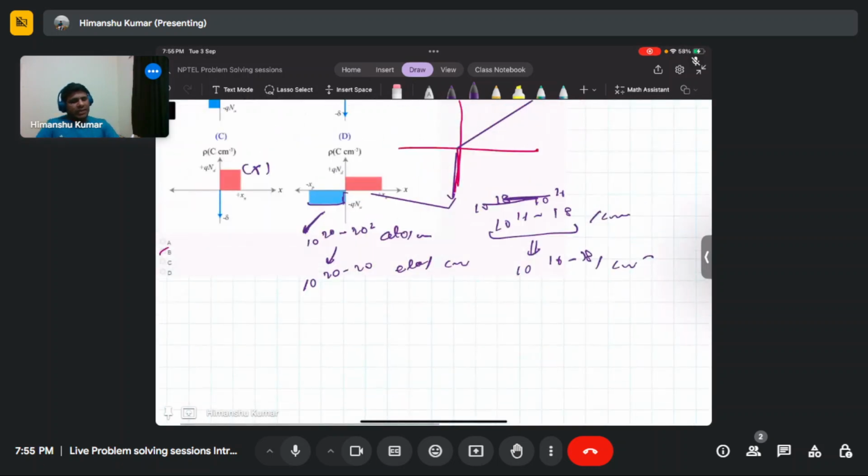So even if you consider a depletion width, basically the metal side of the junction will have around 100 times less depletion compared to the semiconductor side, and that you can fairly consider as a delta doping or delta charge case. Because of this large difference in electron and hole concentration, the depletion width on the metal side is practically non-existent.